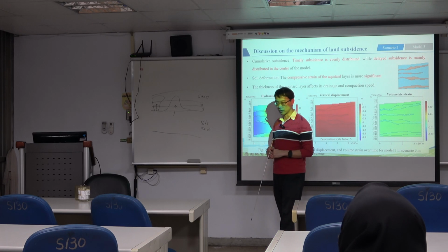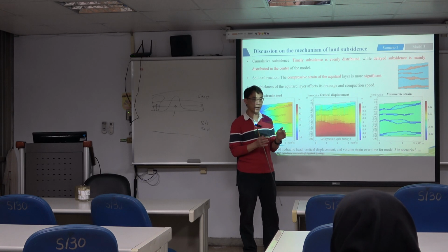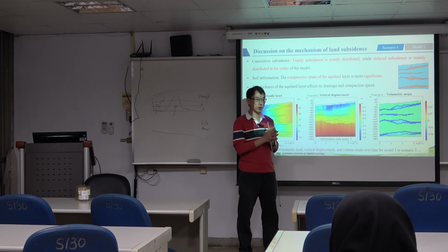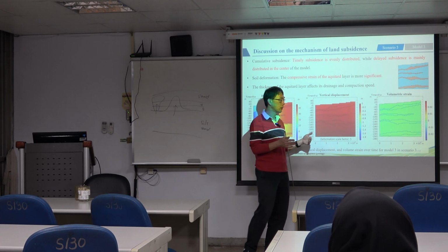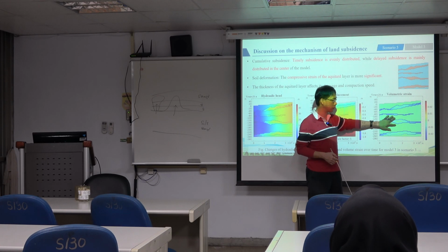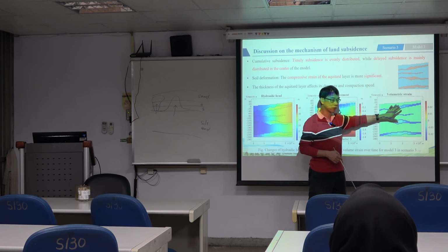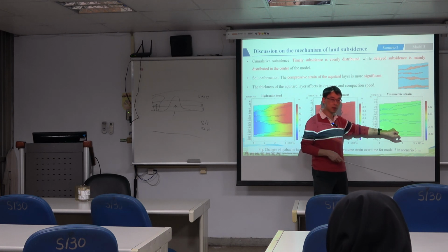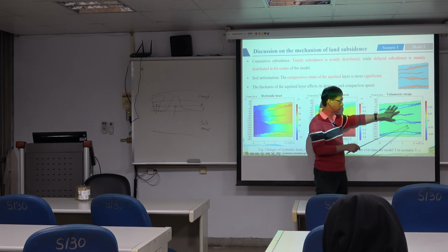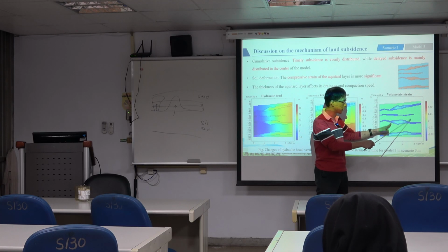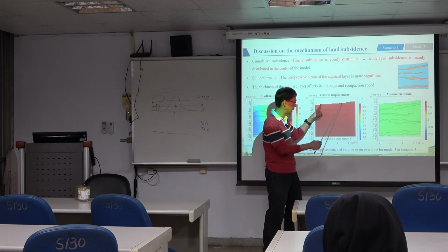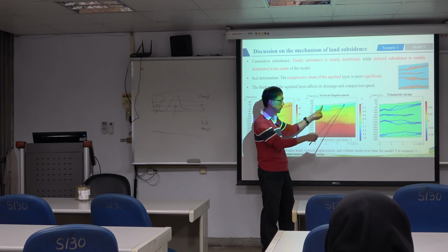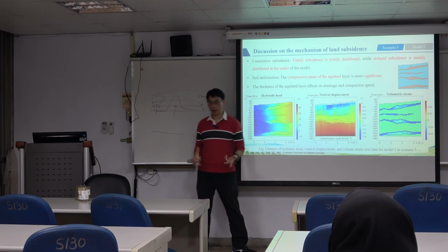Subsidence mainly occurs from clay material because it is relatively soft. So when you have a decline of the head, your clay thickness will mainly control your compaction or subsidence. So you can see clearly this one is more thick, so this area will have larger subsidence quantities. Okay, it matches our expectation.